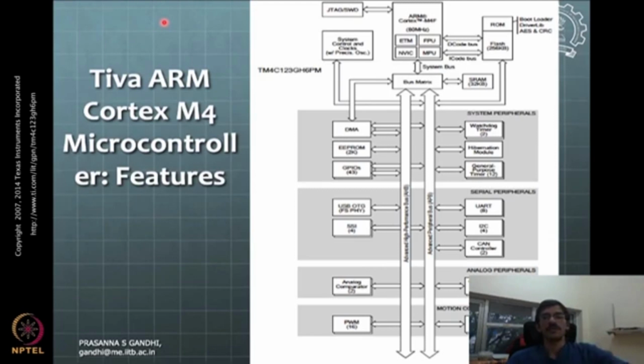To be displayed on your desktop, so that you see, when you run some program in the microcontroller and execute this command, this happens to this register. All these things you can see, and also if you want to record some signal in time, you'll be able to do that through such an interface. So this is JTAG or SWD. Those kinds of interfaces are there.